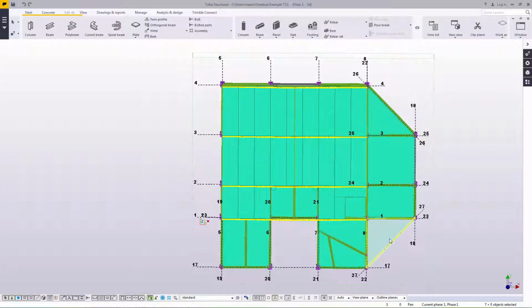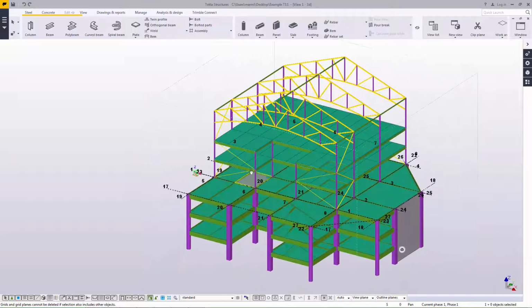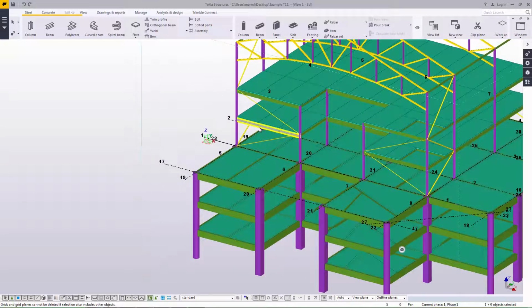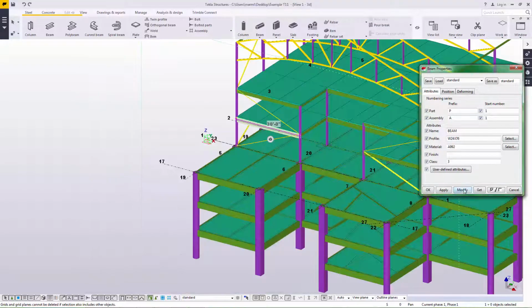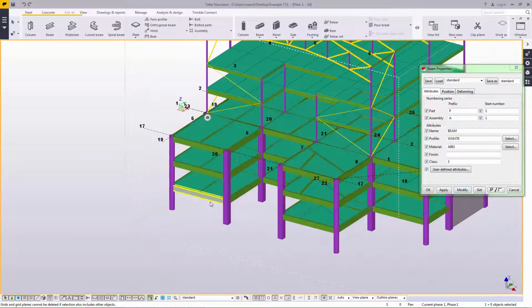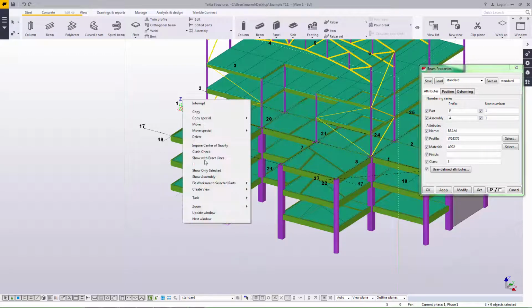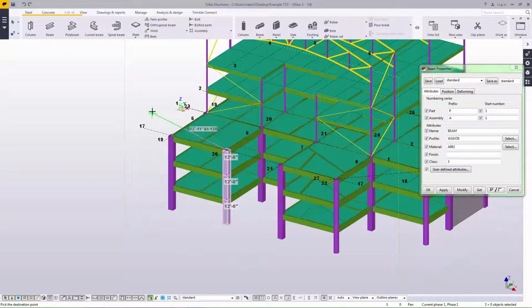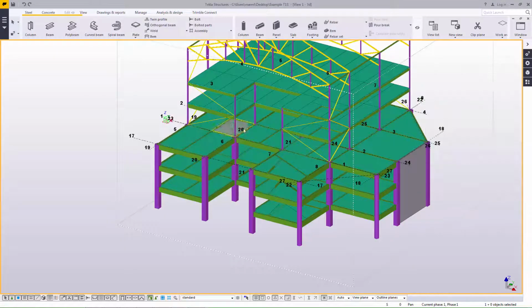We can delete a portion of the building by orbiting the model to suit, and then using a crossing window to select and remove a portion of the concrete structure. We can change one of the beam members in size, so that will also be communicated through to Tekla Structural Designer, and here we choose to increase the section profile. The final changes that we will make will be to delete the 3 stacks of circular columns and to replace these with rectangular concrete shapes, so that the BIM status coloring can be shown in Tekla Structural Designer. We use the Copy command here to perform the replacement.